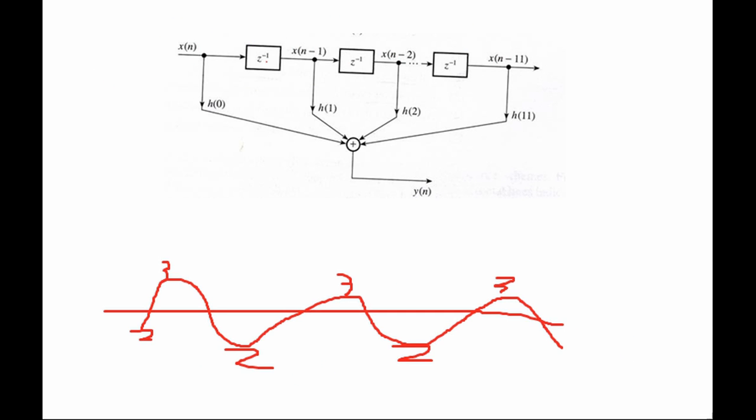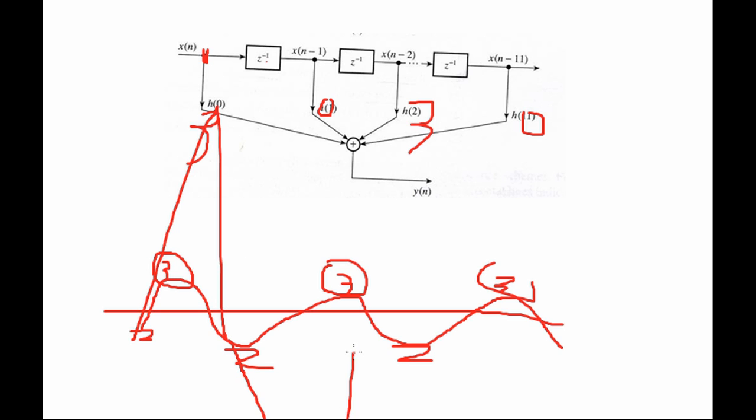So you can see it's an averaging filter, and by now you probably thought, okay, that's very well, but how do you do a high pass filter? Now if you look at it mathematically, if you want to increase your peaks, then it means you have to add this one with that one with that one. So if you do your calculations right and you say, maybe I want to add this one with a big multiplier and that one with a big multiplier and these with maybe no multipliers, if you do these coefficients the right way, it's actually not going to take the average, it's going to increase these peaks, making it a high pass filter. It's increasing the higher frequency, if it makes sense.